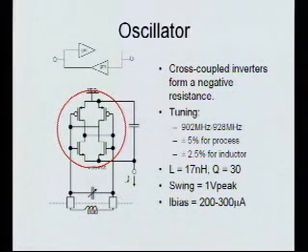So that's great. Now how do you control the frequency of oscillation? You typically vary this capacitor. And in this case, our requirements were, we wanted to cover the US ISM band, which is just a band from 902 to 928 megahertz. But we wanted to cover it in spite of variations in process, so capacitors and transistors vary, and also variations in our off-chip inductor. The nice thing about this is, remember that resonant frequency goes as 1 over the square root of LC.